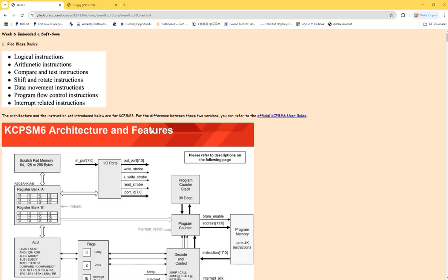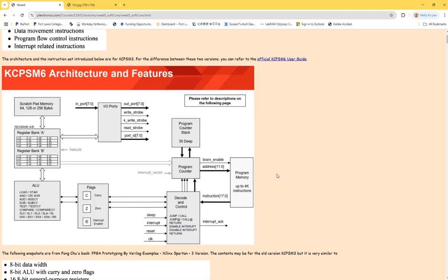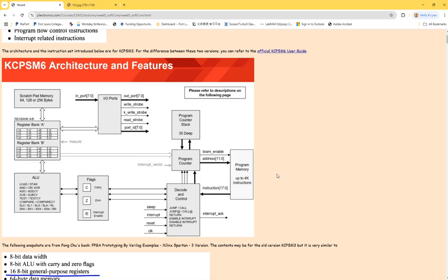This is really exciting because we are basically making a microcontroller on FPGA. It's a soft core. It's not a hard core. So the difference is we use Verilog to program all the lookup tables and logic gates to make a CPU or microcontroller in it. So that little microcontroller is developed by one of the engineers in Xilinx. I think it's just for educators and students in college. It's not a commercial core, but we can still do a lot of things, including program assembly and load the code into it, so the instruction pointer is able to take out every single instruction each time and eventually put in a CPU for computation.